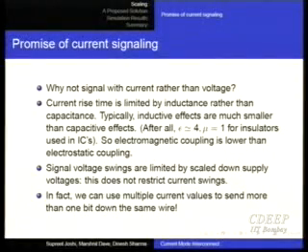Correct. So therefore, because the voltage swing is now much smaller, you will change both delays roughly in the same order. In current mode, you will strictly scale them in the same order. In voltage mode, what happens is that one is rather exponential, so you don't quite scale in the same order. But if delta V is small compared to V, it's quite linear. So therefore, the optimization becomes delta V independent. Okay. So now we suddenly wake up, rub our eyes and say, I got an idea. Why don't we do it differently?